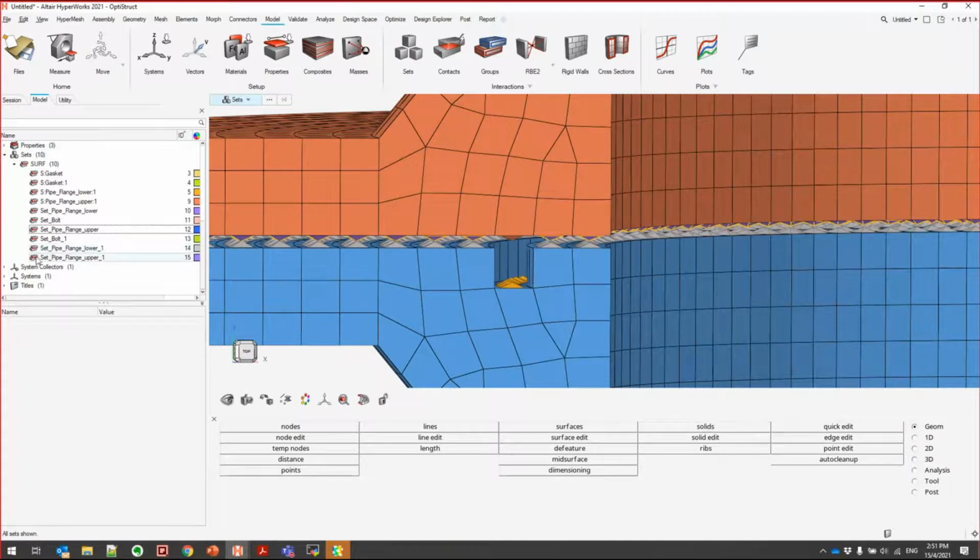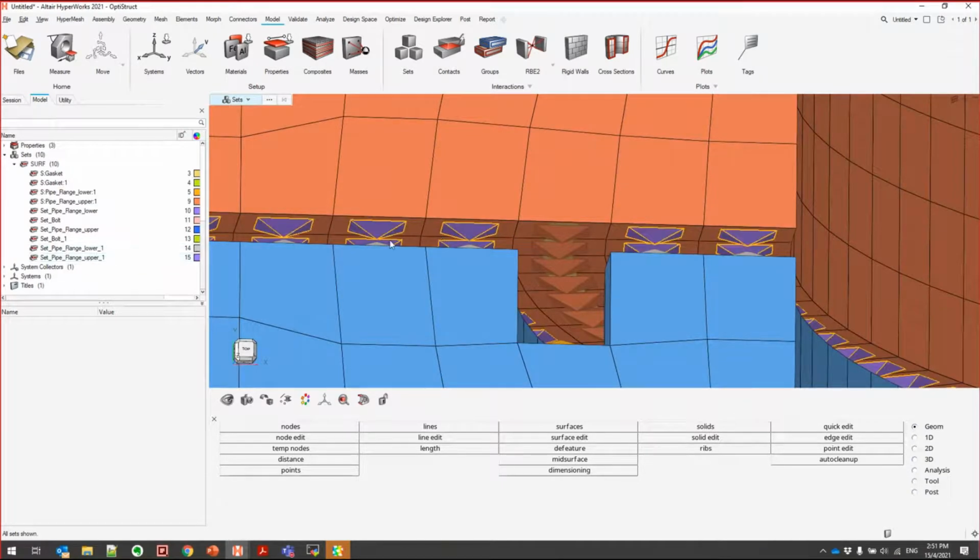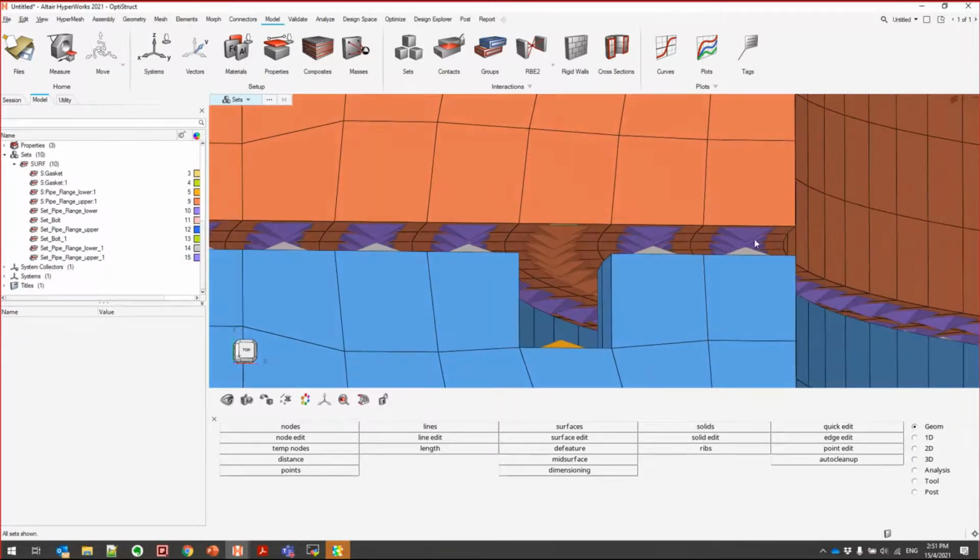Okay, now this is better, right? For these two contacts here, even though they are just two IDs, they have different regions. So this is the front region, this is the rear, the back region. So probably you want smoothing on just the front region and not the back region. Then you need to create different sets for them. Now there's only one contact set. You need to define another area where you only apply smoothing. So let's say I'm going to apply smoothing on the front area only.